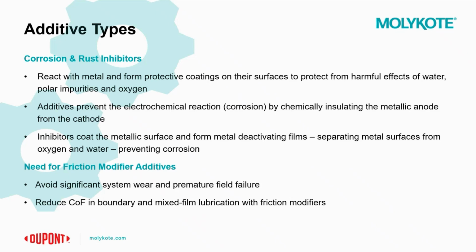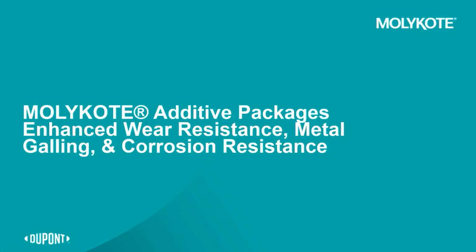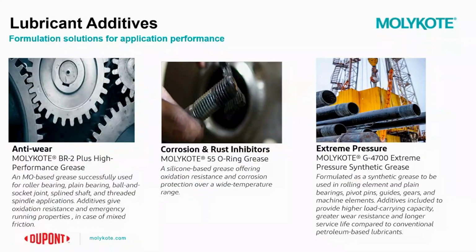So if using a grease or a lubricant without additives, the contact could eventually lead to significant system wear and eventually premature field failure. So the incorporation of a friction modifier additive could ultimately help you significantly reduce the coefficient of friction in these regimes and eventually delay field failure. So next we could take a look at some specific MOLYKOTE additive packages for enhanced wear resistance, metal galling, and corrosion resistance. So we'll start by taking a look at the different MOLYKOTE grades that could be used for specific